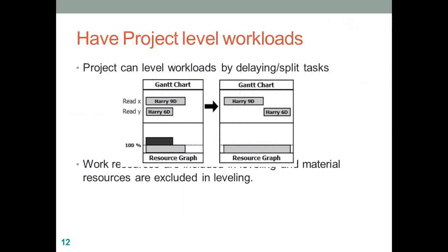Let's look at the next option by which you can do automatic leveling in Project 2010. So the last 20 minutes I have been doing optimization in the manual way. When I say manual way, I was finding out which resources are over allocated, and I was also either delaying that activity to the next available date or swapping it with another resource. So all these are manual options.